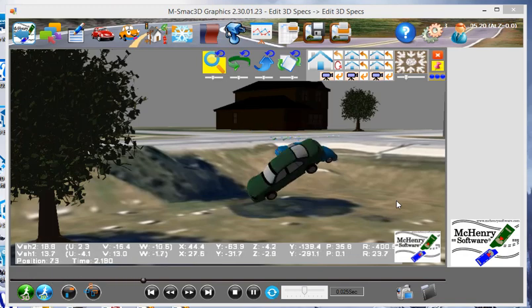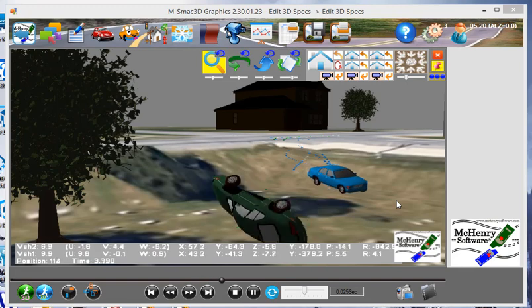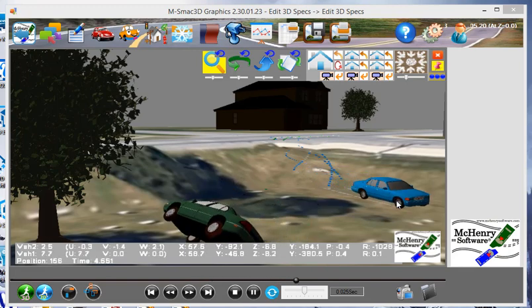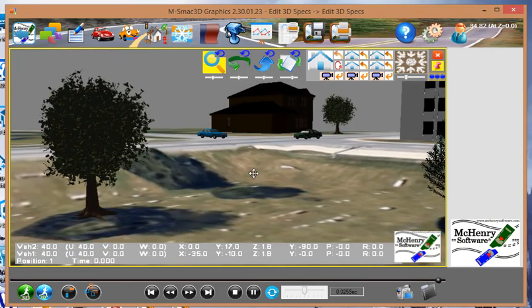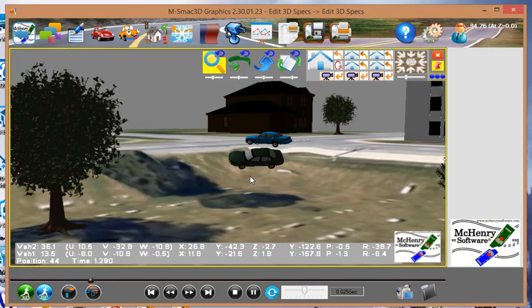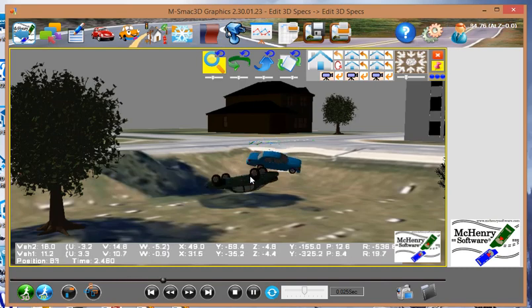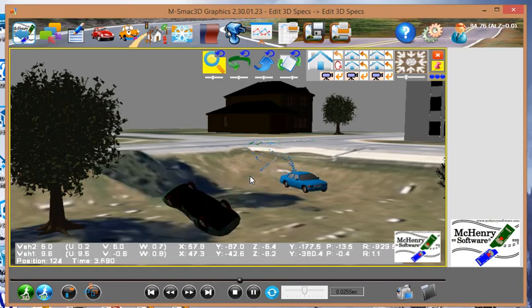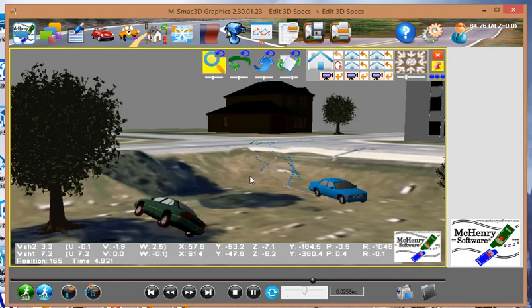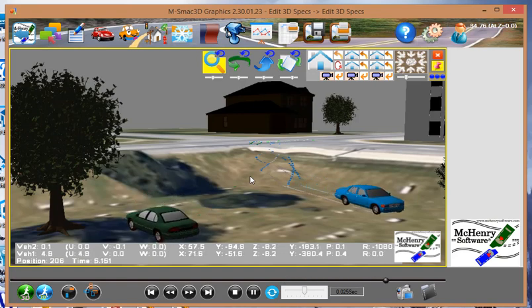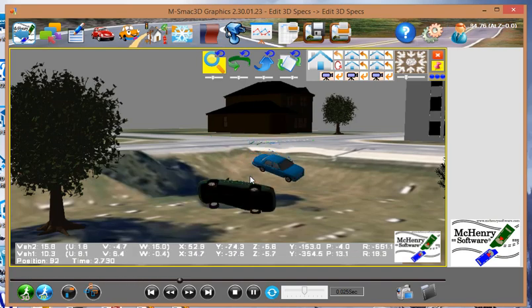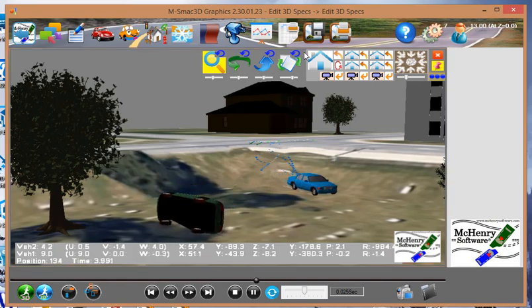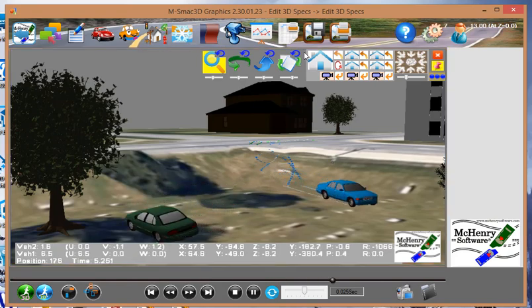This is a quick overview of how to change specifications for the 3D simulations that you are doing. If, for example, you get some measurements of a car from a manufacturer, from MVMA specs, or if you actually just happen to measure it, things like the stiffness of the suspensions, the extension in jounce and rebound, bumper locations, things like that, they may be slightly different than our approximations. So I'll show you how first to determine what the actual approximations are and then how to change them.